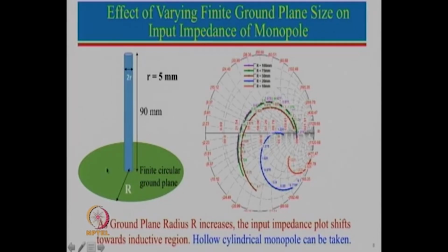But suppose it is put over here, then the results will change, or if it is put here or over here. So results will change if the location is changing. And suppose it is a rectangular ground plane of a smaller width and a larger length, then again the placement of the monopole antenna plays a very important role, and one really has to properly simulate these cases.